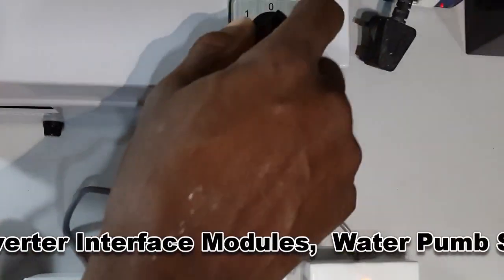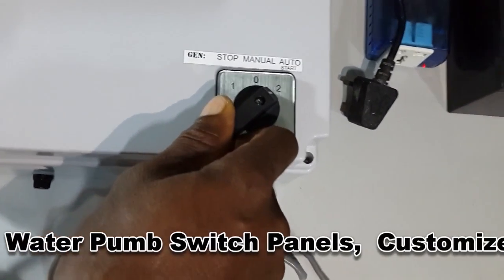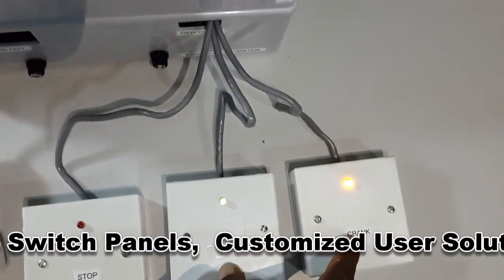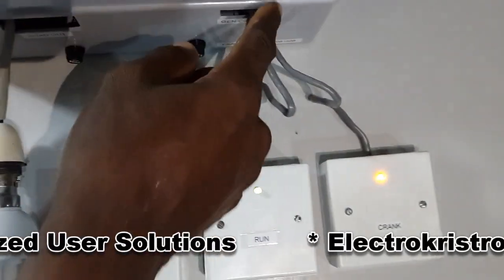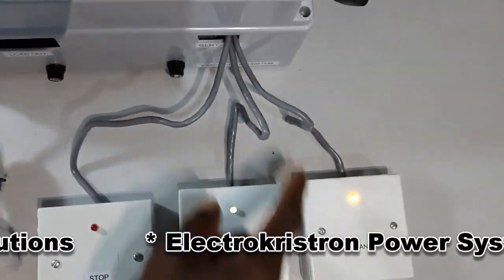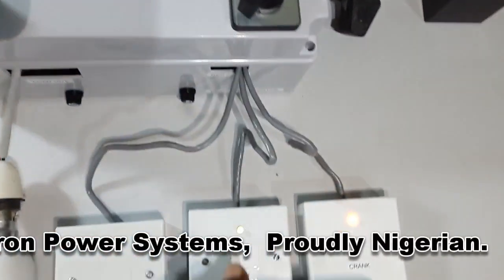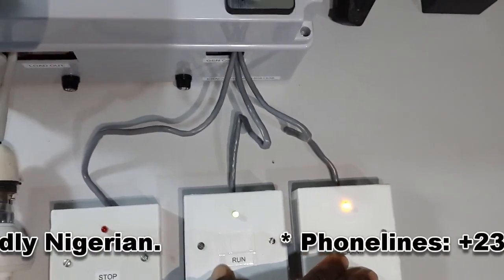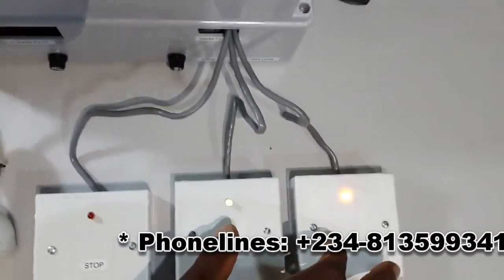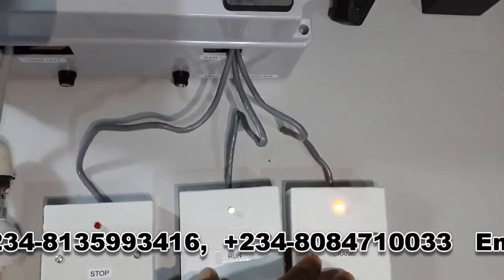Now the moment you switch on the AutoStart switch, the commands are given to your generator to start, provided there is a link wire that has been run from the automatic changeover to wherever you have positioned your generator. So this will actually connect with the key or ignition system of the generator.